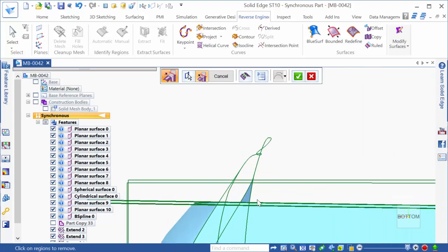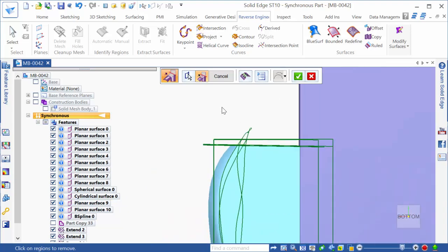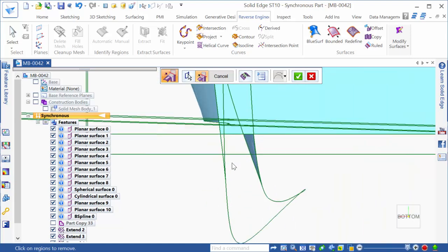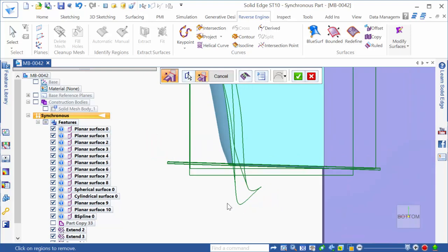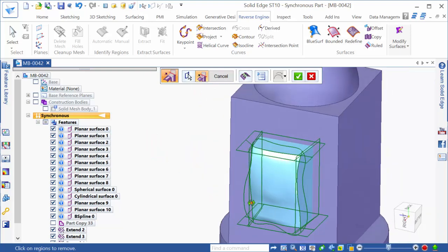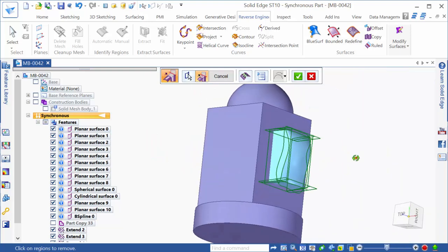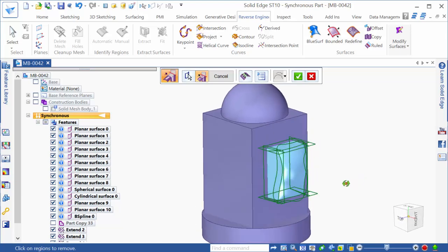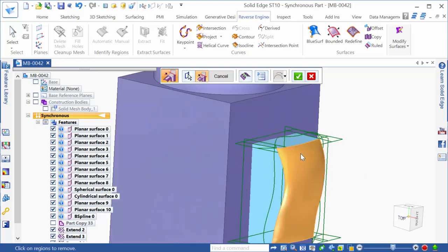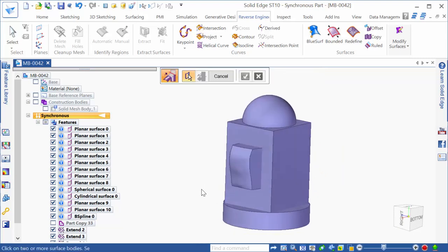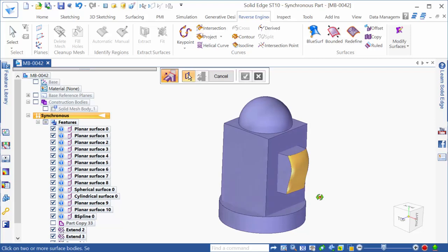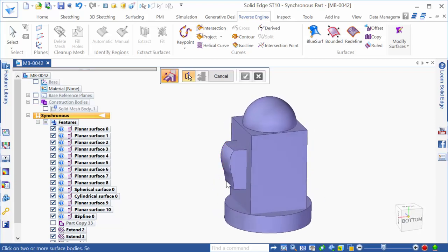Right, and you have to pay attention as well because there's a couple of the little guys left over, depending on how accurate the original set is whenever you create the surfaces themselves. So it looks like we got everything taken care of here on the outside edge, and then go ahead and right click, and you'll notice that we've got all of our surfaces trimmed together.